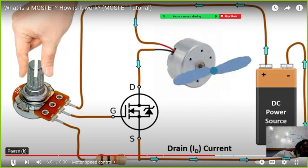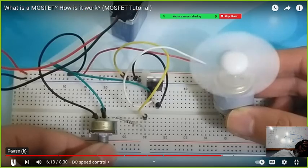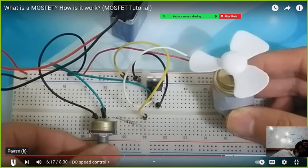By connecting a power supply that provides a constant 5-volt voltage instead of a potentiometer, while the MOSFET is triggered above 5 volts, it is not triggered at the voltage below. For a better understanding of this motor speed control circuit, I built the circuit on a breadboard.